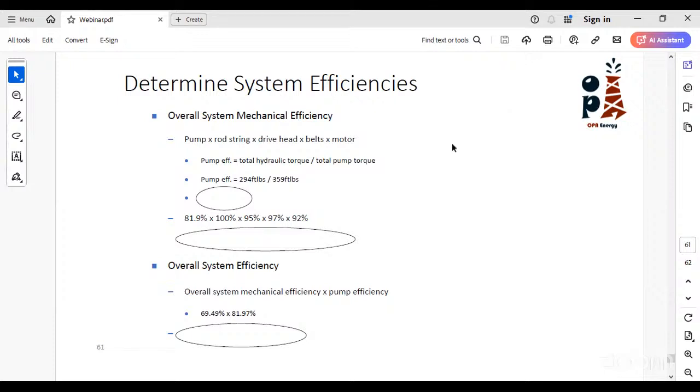In unconventional wells, for example a very highly deviated one, or even a fractured or high pressure, high temperature well, or even wells with thermal stimulation, as I told you, the factor that is constraining or limiting our design is the elastomer and the bonding between the elastomer and the stator.